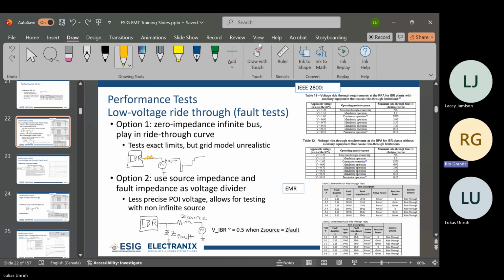And so Alex, that's the multiple faults, right? Multiple low voltage ride through. And what's the timeline? Is it 30 seconds or is it on the minute? Something like that. I think it's 5 and 30 seconds. 5:30. But this one is still like these 2.5, you can still spread out over some cumulative window that's different from that one, right, though?